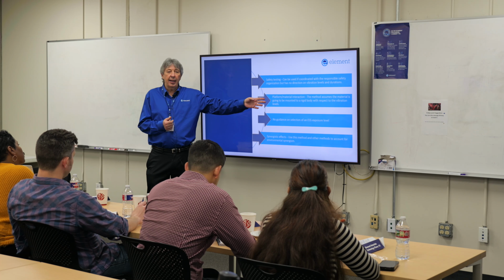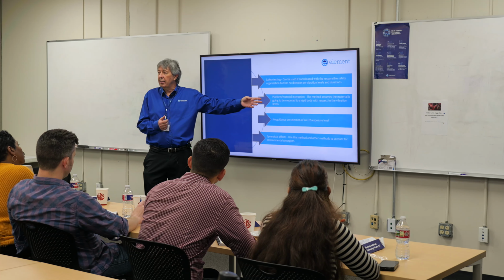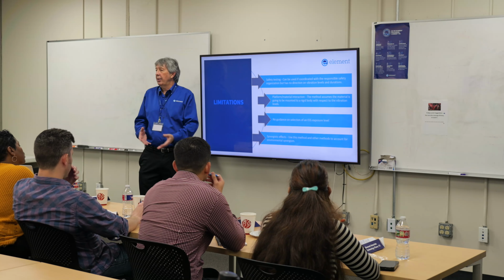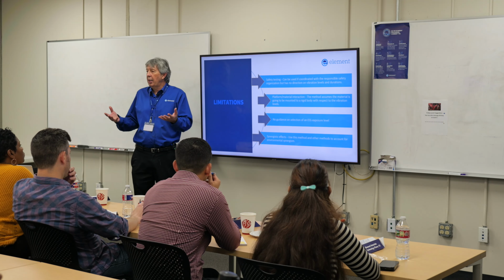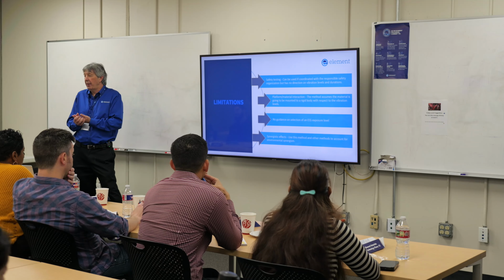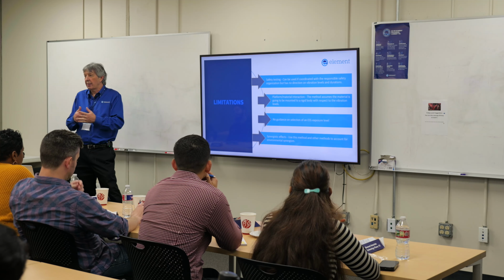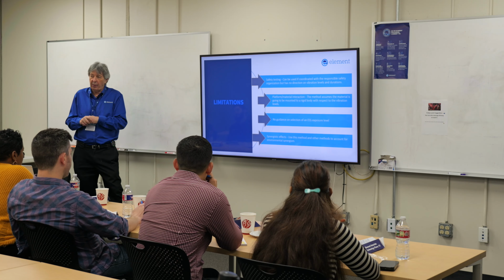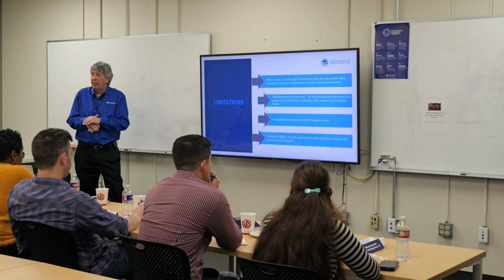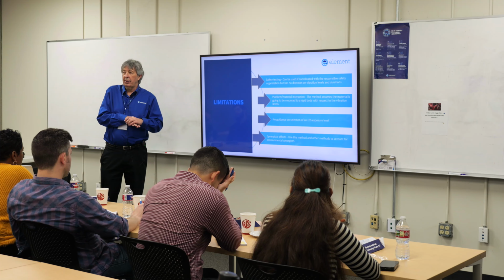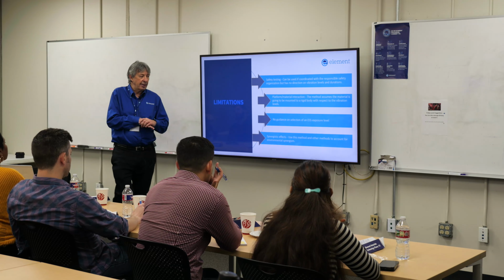And 810 uses what's called Gaussian distribution. So if you're on a system that's responding and your unit responds to that system, you might not have Gaussian distribution of your random either. So that's when you get into this kurtosis stuff, which we're not going to cover today. But so you just be aware of that. So we assume everything's rigid. Our fixture is more rigid than the system it's going to be mounted on. We try not to introduce any resonances.